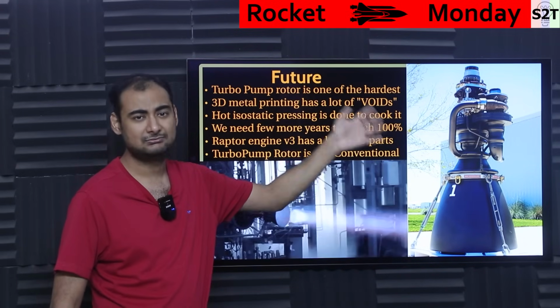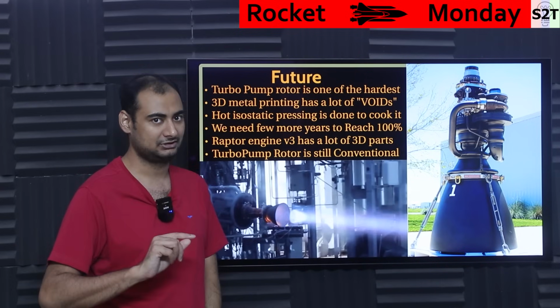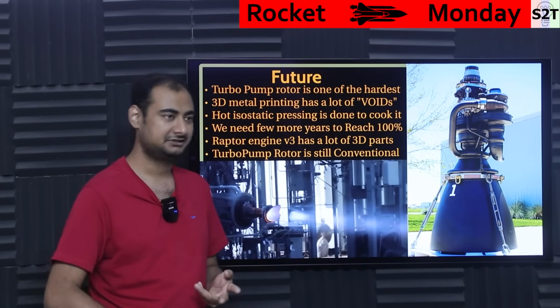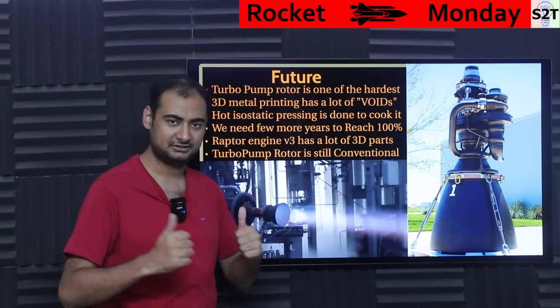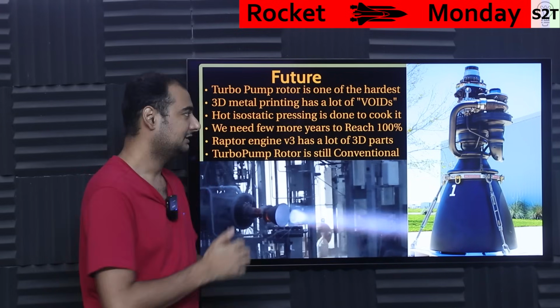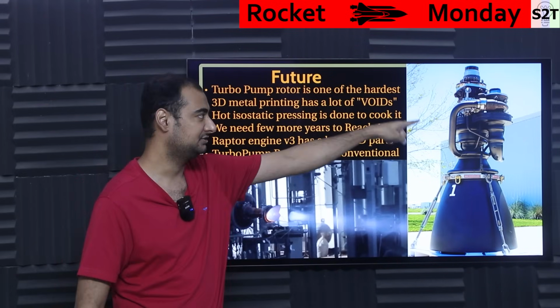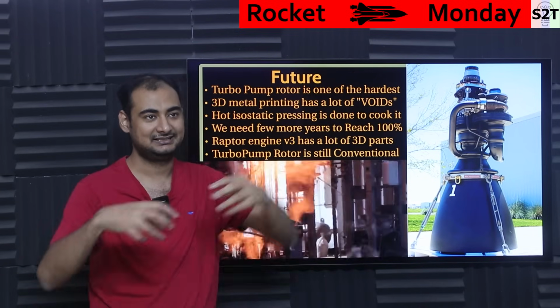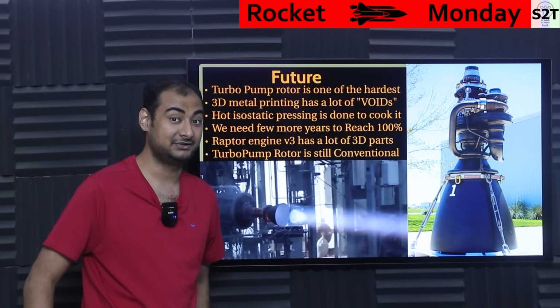Can anybody do this? More or less nowadays, yes. It's just that you still can't touch a rotor. Injector plate, got it. Turbo pump geometry outside the casing and all that, got it. Nozzle, got it. Combustion chamber, got it. Turbo shaft, no. And that's why you see a lot of bolts in that area. It still needs to be opened up so you can put the turbine in. And again, look into how they are dealing with the bearings.